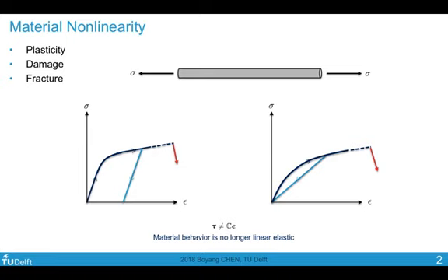Today we are going to talk about material nonlinearity, and we'll start with plasticity. In the first lecture, we've introduced material nonlinearity as a behavior deviating from linear elasticity. On the left, we have a typical yielding type of behavior, where under loading, the tangent stiffness becomes smaller, and then under reloading, we retrieve back the original stiffness, Young's modulus here in the one-dimensional case.